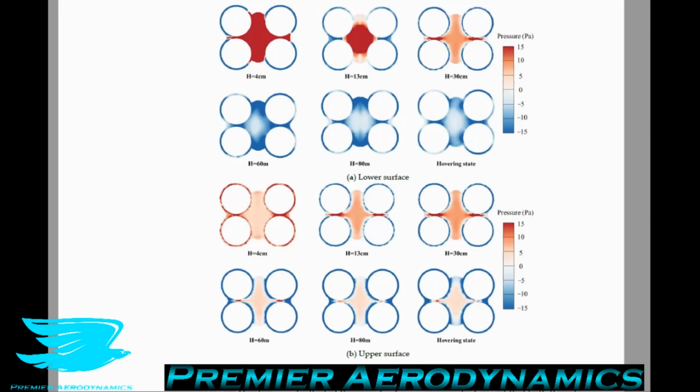The downwash effect of the parent rotors causes a reduction in lift of both the rotors and the body of the child UAV. So again, when the propellers are working, you're sucking away flow from the child UAV, and that's reducing the lift, unfortunately. On the one hand, according to the blade element theory, which is a theoretical way of calculating not only the lift but also the thrust of a propeller, it's easier to do than regular CFD because you don't have as many properties to calculate, so it's quicker, but not as accurate often. But it depends on the situation.